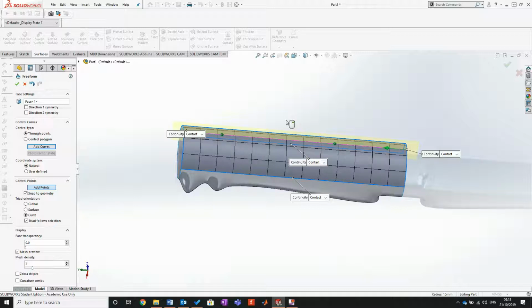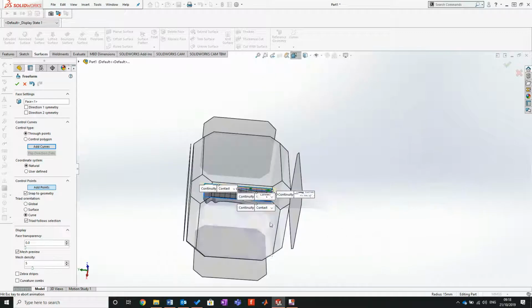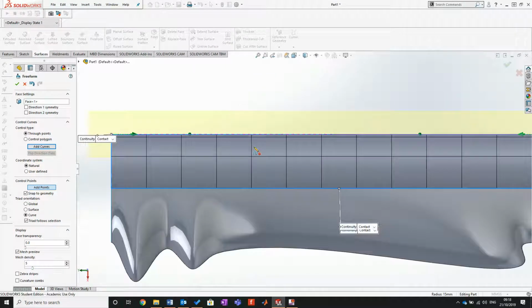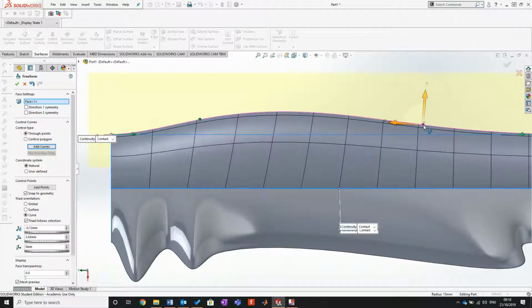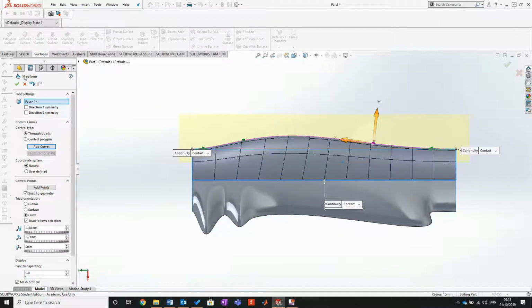Now, some were saying to me last week, how do you place them? So this is placed like this, but because I know I want it to really move, I want it to be deformed around the YZ plane, what I'm going to do is just look on that plane there like that. If I don't, it could easily lead me to a position where when I manipulate, it will move in all 3 planes. So looking on this face will just restrict that level of motion, because it knows it cannot move, it has no understanding for it. So I right click, and then I'm just going to move it up, something like that, and then to something like that. So click OK.